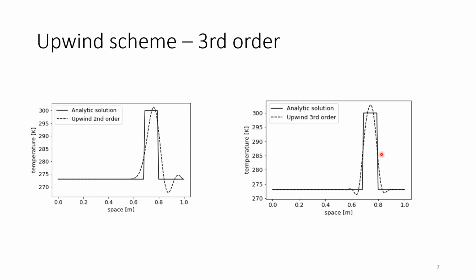If you deal with advection, there are a lot of different schemes, flux correction, and whatever they are called. They're also methods trying to estimate the numerical diffusion effect and then reverse it. So, a bunch of possibilities. But I'm making you familiar with a few methods here today.